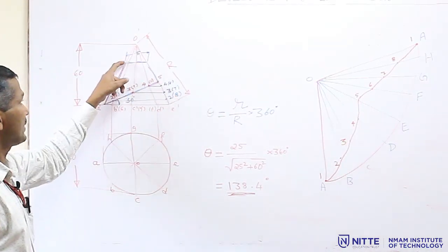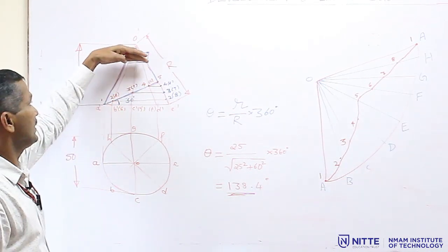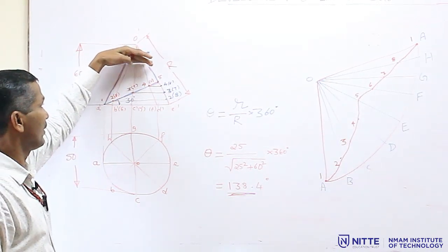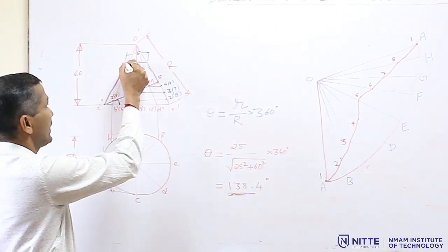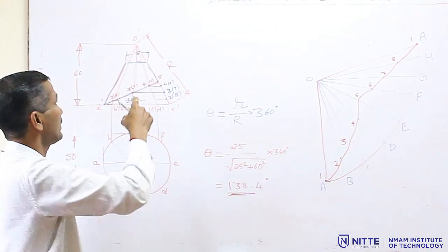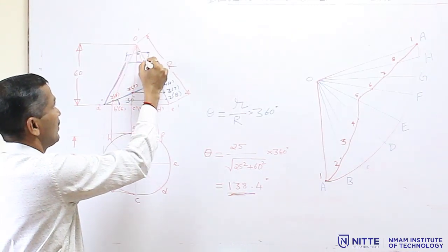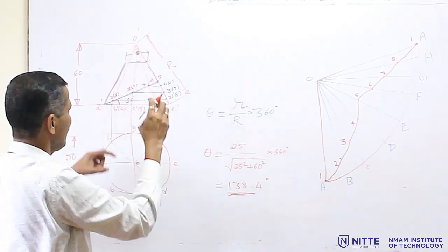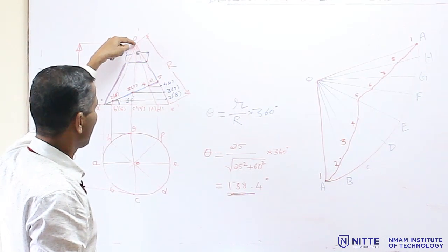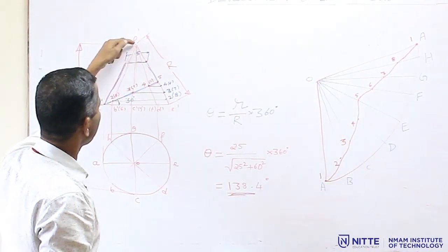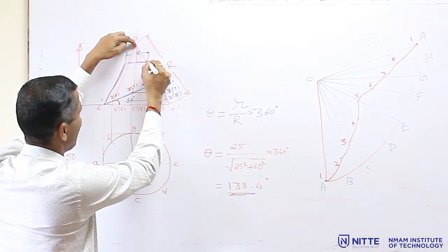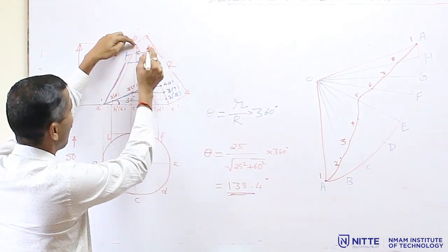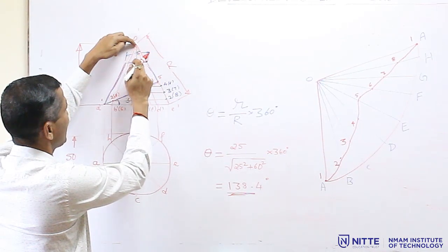Then there is one more section part, and since this section plane is horizontal or parallel to the base, marking the section points is not necessary because all these section points will have the same radius. So, that is why take the compass and measure this distance on the true length of the generator from O up to here, not on the remaining generators.